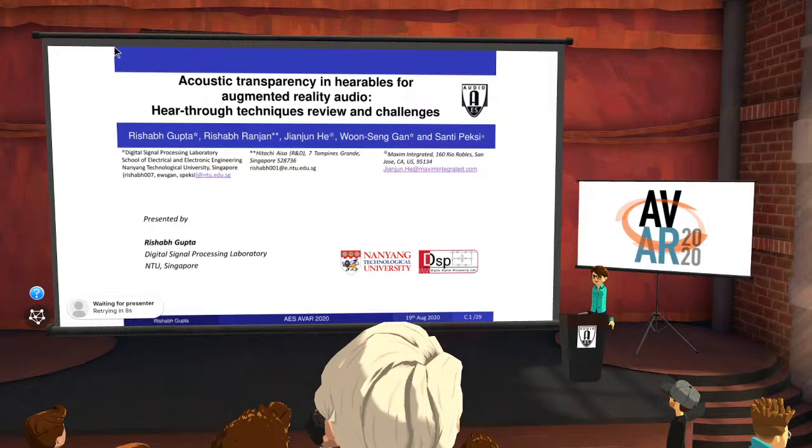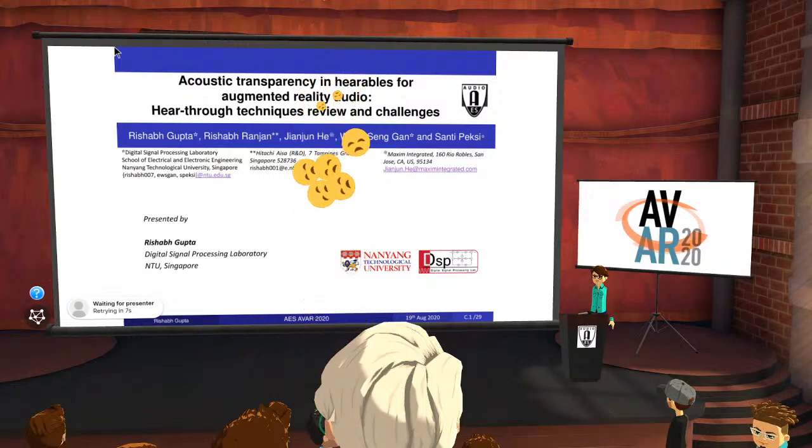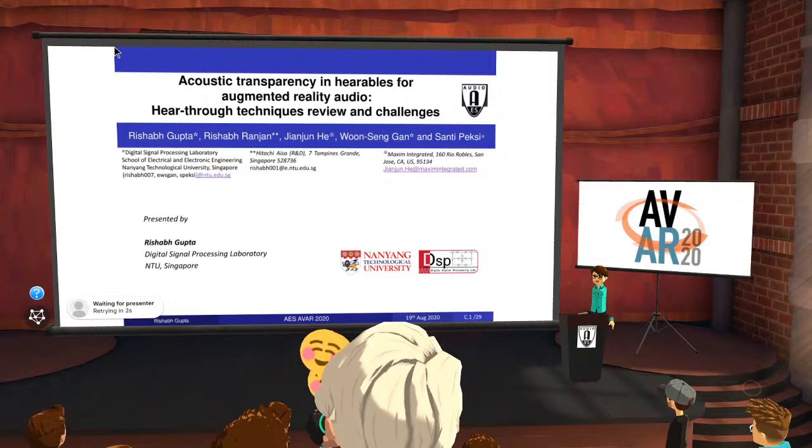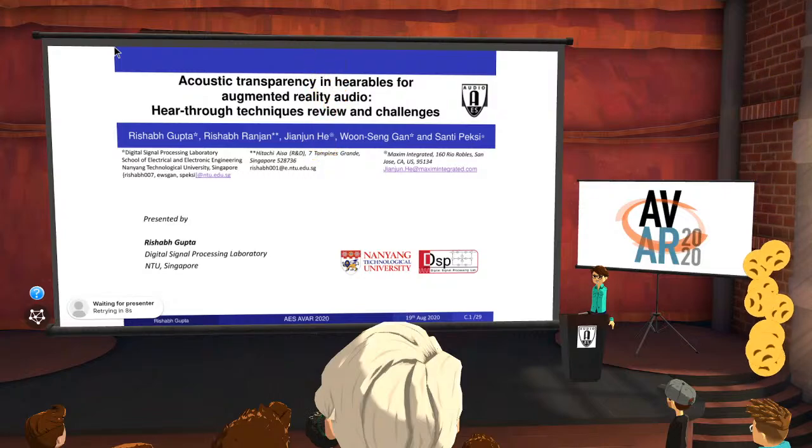So we're all experiencing AltSpace VR, the spatial audio teleconferencing, and it's quite beneficial to have spatial audio in teleconferencing. The way it works here is that we have the individual recordings of the speakers and also the knowledge of the speaker locations. And so we can use binaural rendering. And if you are lucky, you're using an HMD to listen to this, then you have even head tracking, which improves binaural rendering, makes it more natural, and gives us improved localization and reduced front-back confusion and in-head localization.